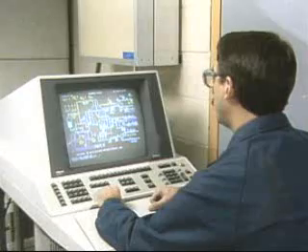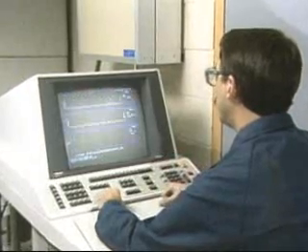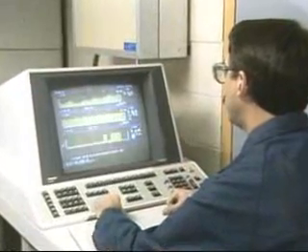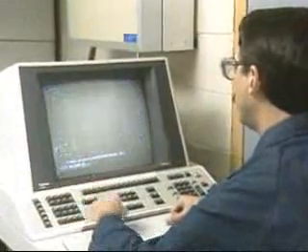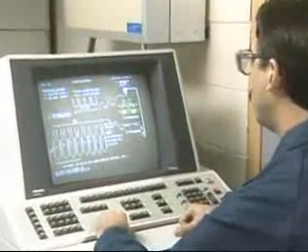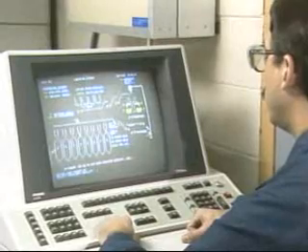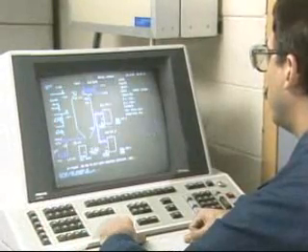There are several different types of process unit digital control systems. The differences between them are mainly in how the control function in each system is arranged. A major characteristic of supervisory control systems is that the supervisory computer does not directly control the values of process variables. Instead, it directs the activities of the process controllers in the system.